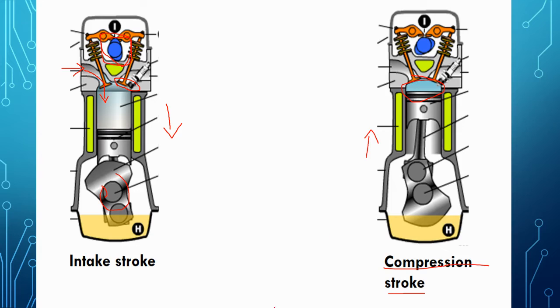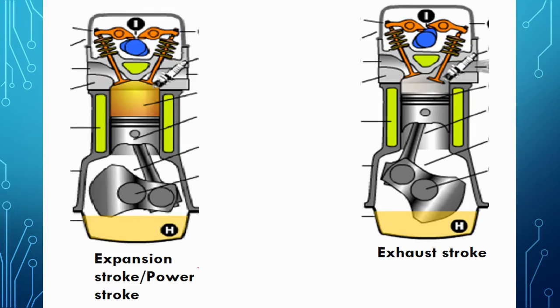As it gets compressed, high pressure and temperature are created. Now what happens if we ignite this with a spark plug placed at the exact place, which gives out a spark, burning the fuel and pushing the piston down with an enormous amount of energy? That is the reason it is called the power stroke. Even in this stroke, both the valves are closed, and as the spark is given out, the fuel expands and pushes the piston with enormous power.